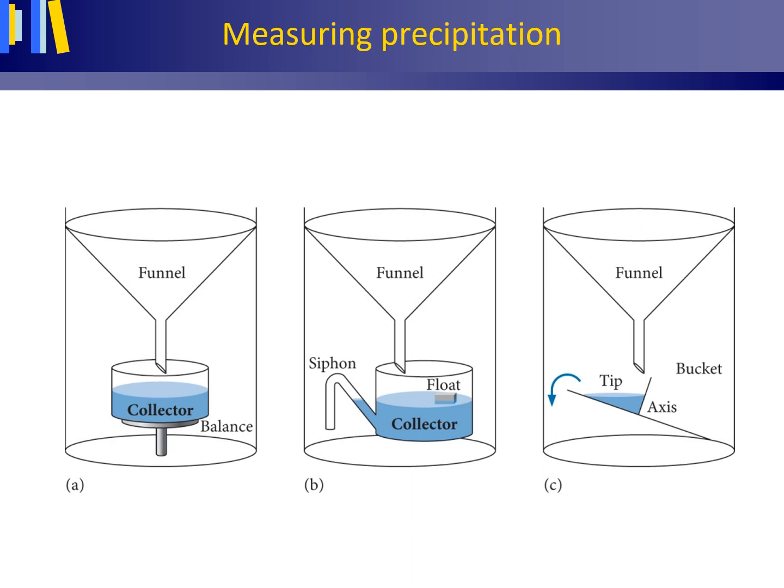The rain gauge is an obstacle to wind, causing turbulence, and as a consequence, raindrops may be blown out of the orifice, leading to an underestimation of the rainfall depth. The higher the orifice, the larger the wind speed, plus the smaller the water droplets, the more pronounced the undercatch of the rain gauge will be.